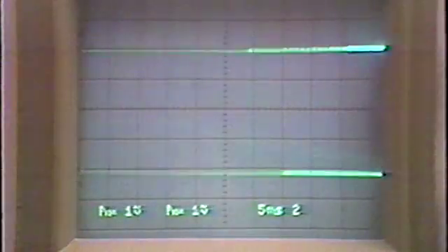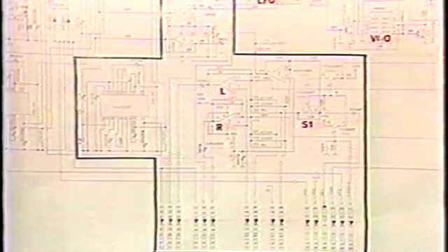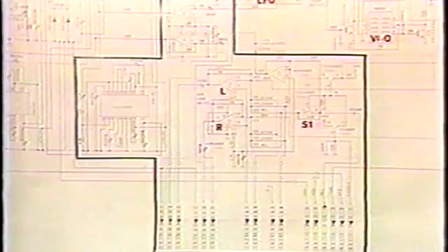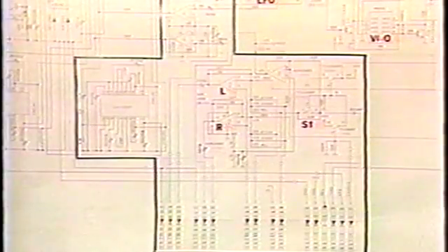Oscillating sound is shown at the top and white noise at the bottom. The signals for melody, percussion, bass and chords enter the left and right mixers where they are mixed. After being output by the mixer, these signals pass through the main volume control and enter the power amp. After being amplified by the power amp, the signals are output from the left and right speakers and are heard as sounds.